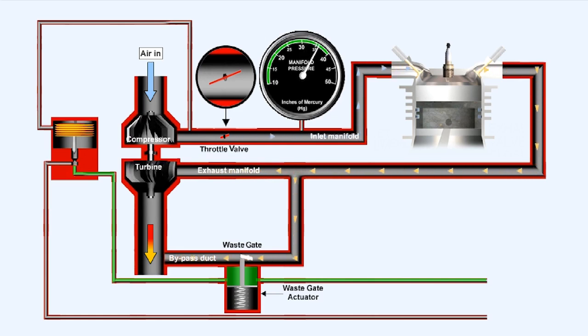Initially, the inlet manifold pressure will rise. The absolute pressure controller will sense a drop in compressor output pressure, and the aneroid capsule will expand to close the oil bleed valve, increasing the oil pressure in the wastegate actuator. The wastegate will close in response. The new wastegate position diverts more exhaust gas to the turbine, which accelerates. Compressor output rises in response to the increased turbine speed. As a result, the inlet manifold pressure will rise again, and so on.